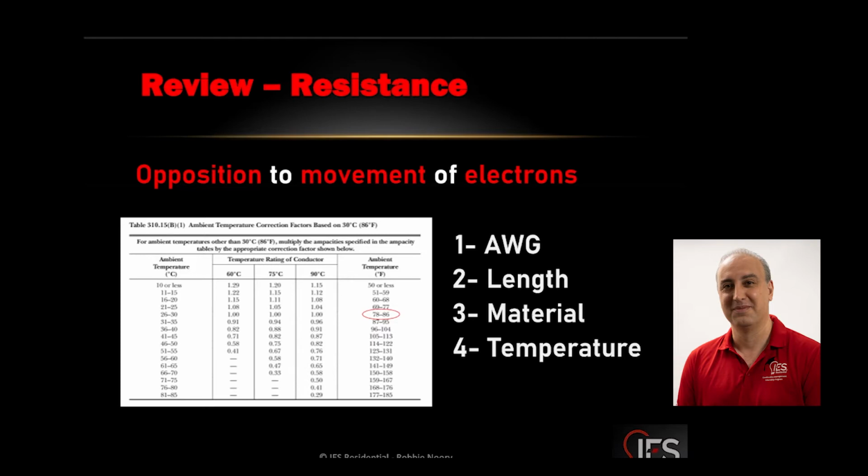When you look at, let's go back to the 60 degrees C. So Romex falls under that one for us. So look, it says your correction factor is 1. 1 means there's no correction. You multiply something by 1, it's the same thing, right? Nothing changes. What it's telling us is that if you're in this range, the ampacities that you saw in the last table, 310.16, is what you use.